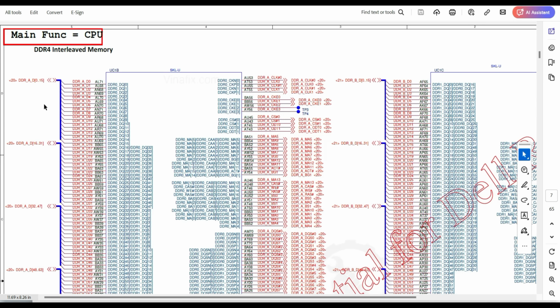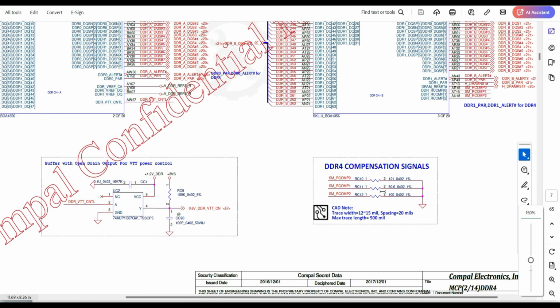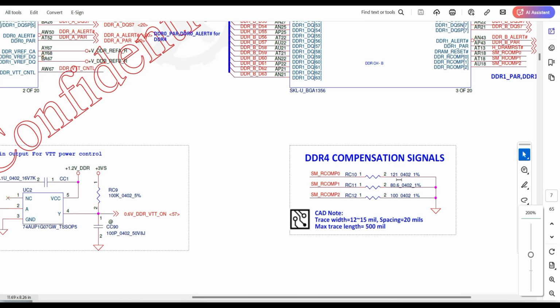And here is the pull down. Here may be voltage or it may be 0. 100% it's a 0 because it's connected to the ground. Here it may be voltage; it depends on the active component. See, here is the pull up 3 volts Vs, and here the destination pin number 2 may be 3 volts or it may be some other voltages.